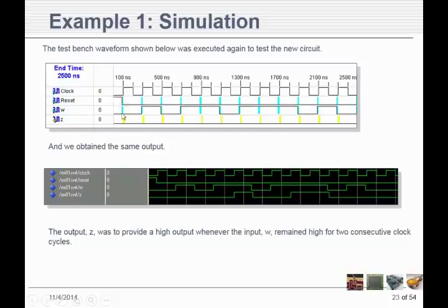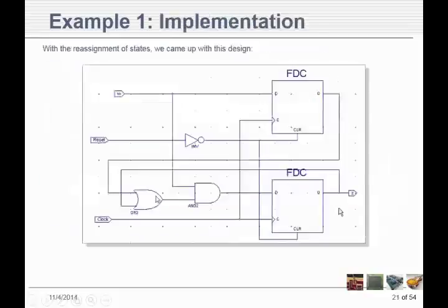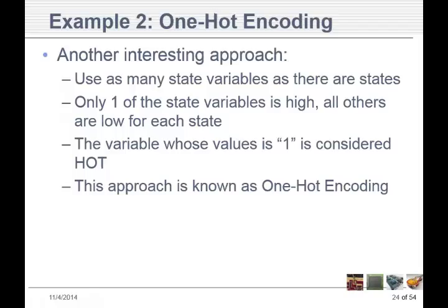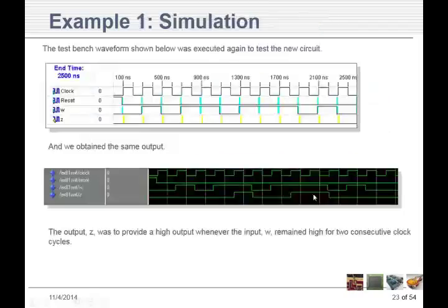You do have to have it at the beginning so that Xilinx will know what the initial output of these are, especially with J, K, and T flip-flops that are always dependent on what the previous state was. If you don't tell it at the very beginning what the current state is, then it doesn't know throughout the whole rest of the timing simulation.